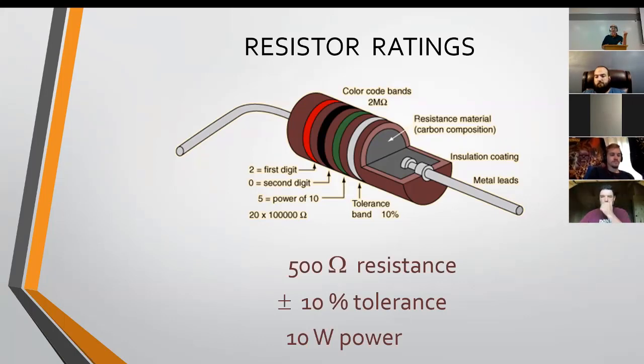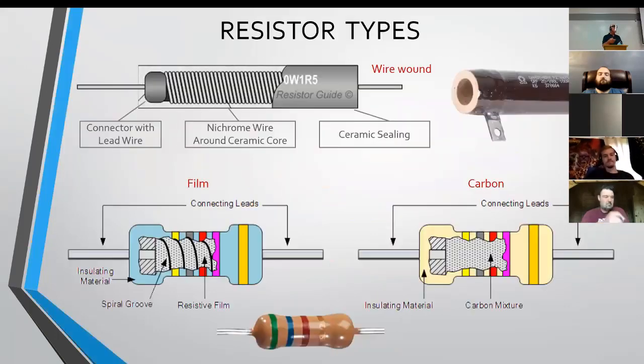For a lot of applications, plus or minus 20% is fine. It's good enough. And you can make resistors with a 20% tolerance a lot cheaper than if you have to make them like at 0.1% tolerance. So most applications don't call for that level of accuracy, so you don't pay for that extra dollar and extra machining. So it gets down to picking the right thing for the job.